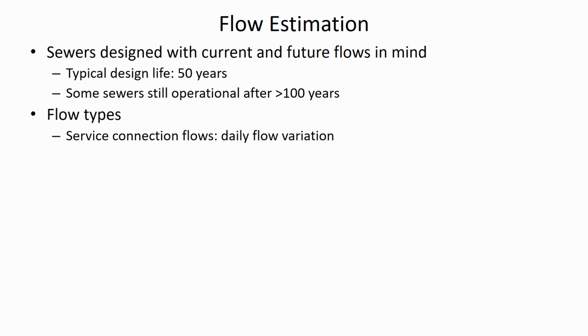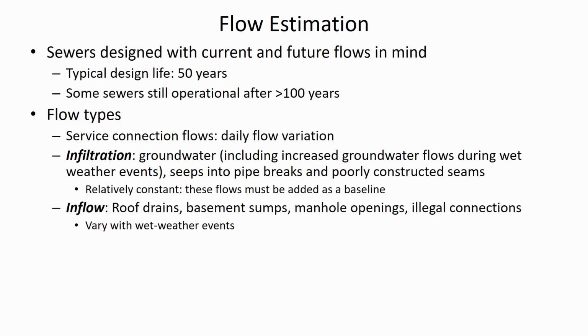You've already looked at that, the curve where they're using a lot of water in the morning and then again in the evening because of the variation in human activity. So there's also a similar variation in when the water is going through sewer pipes. And so they have big peaks down at the sewer plant at night during the same times that people are using water for washing clothes, flushing toilets, taking showers, and so on. So there's a lot of daily flow variation. And the pipes have to be designed for the peak hour in the peak design condition some many years in the future.